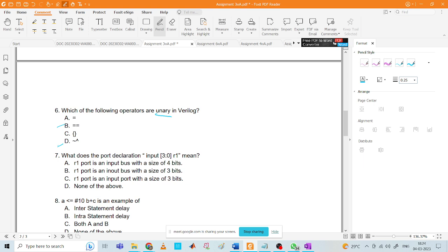Yes. So, and why XOR operations are used in unary? What is the application? For parity bit generation, yes, you are right. Okay. So let's say you have 101101 and you want to generate a parity bit. If you XOR all the values, you will get one parity bit.